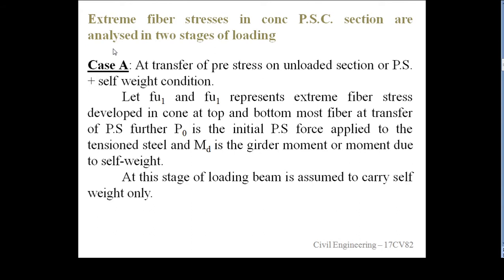Then extreme fiber stresses in concrete PSC sections are analyzed in two stages of loading. Case A is at transfer of prestress on the unloaded section, or prestress plus self-weight condition. Case B is at transfer of prestress on the loaded section, or prestress plus self-weight plus live load. This is the condition, case A and case B.